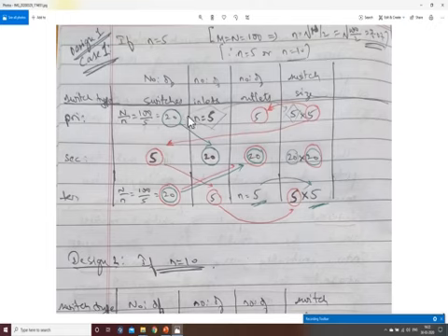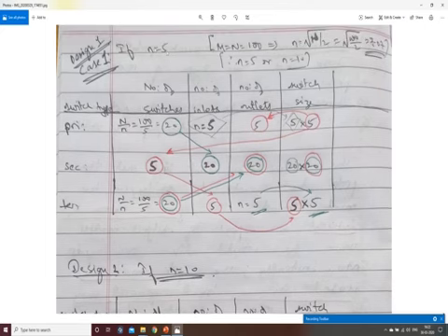Now here I have to decide how many inlets and how many outlets there are. The number of inlets is given by this value itself. So the number of inlets to the primary stage is obtained from n equal to 5. So this is already identified. Similarly, the number of outlets for the tertiary stage is also decided by that value. So these are the known parameters. Now from these parameters I have to estimate the other things, then I have to see what the overall design is. Now when I consider this case, I know that the number of inlets for the primary switch is 5 and I have 20 primary switches.